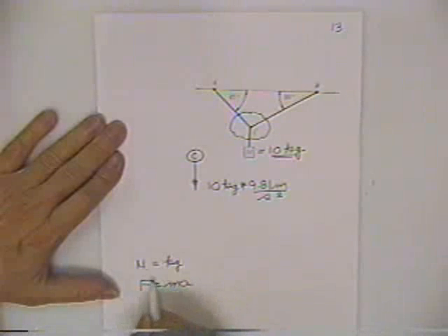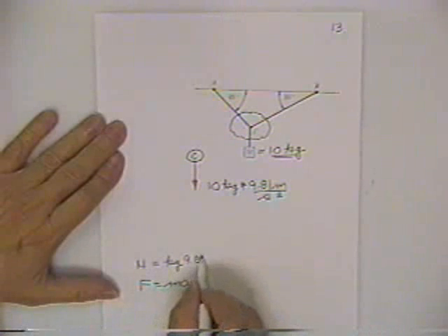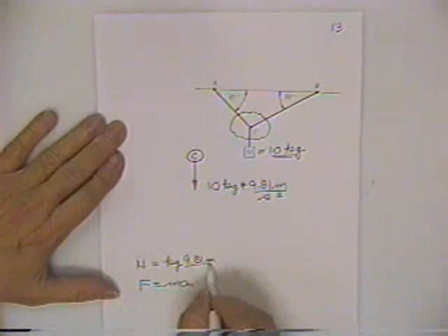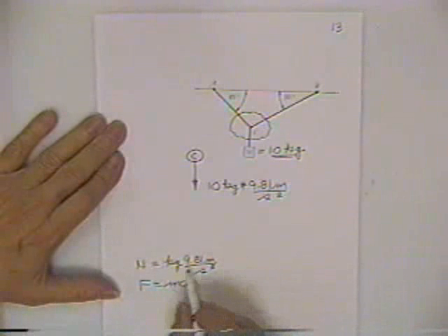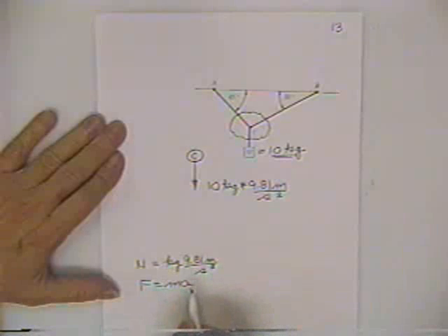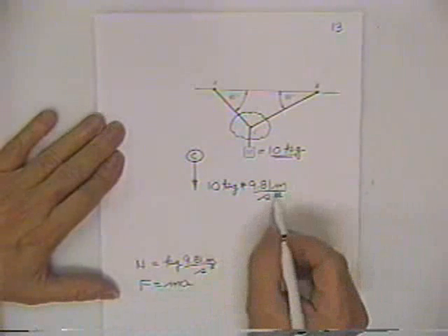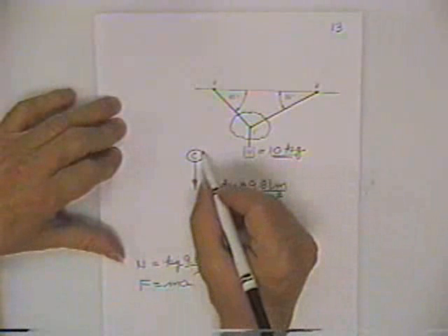What do you have to multiply it by to make it a force? You multiply it times g, and that's 9.81 meters per second per second. And a kilogram meter per second squared is the same thing. They gave that assemblage of units the name newtons, and so that's why we've got to multiply times 9.81 to turn it into a force.